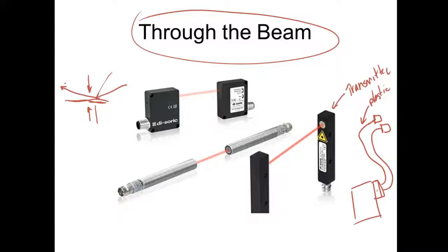As long as you stay below the critical angle, you'll get what we call total reflection. If you exceed the critical angle, then it's going to go through the other object. So that's what we do in fiber optics. We have two types of material, like two different plastics or two different glasses, and they literally put one of the glasses in the center that we call the core, and the core would be embedded in the other glass or plastic, and they're different plastics, so they have different reflections. So what happens is, if we don't exceed the angle, then the light would actually travel down the core.